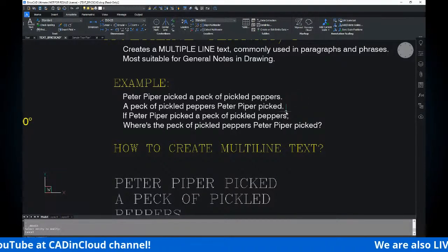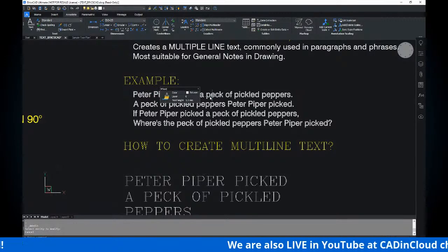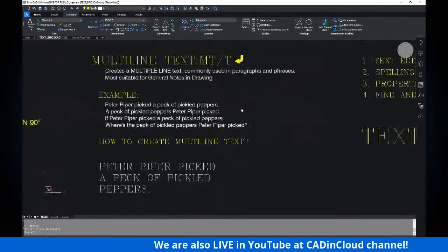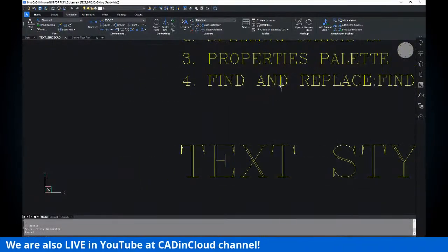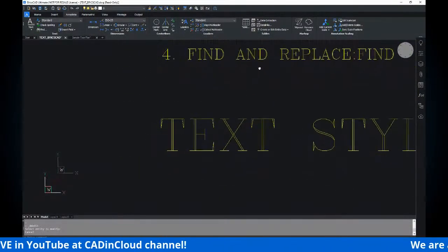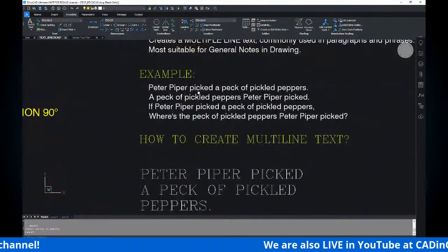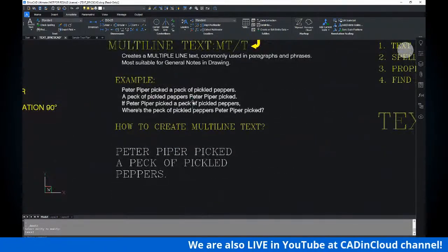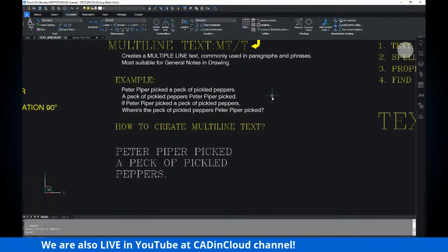So it's very hassle for you to edit manually yung word na yon. So, you can use the find and replace in order for you to easily change that word that you want to change. Don't worry, BricsCAD will display naman kung saan banda yung mapapalitan mo.